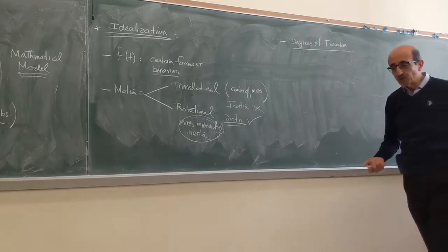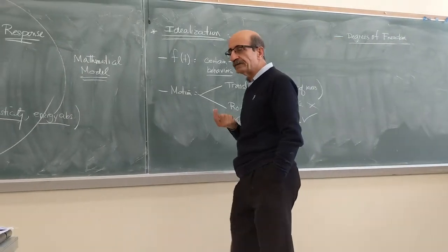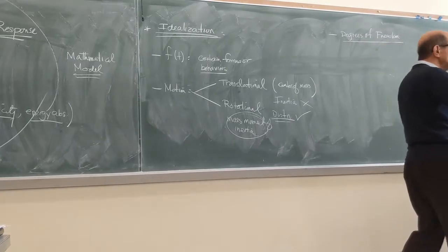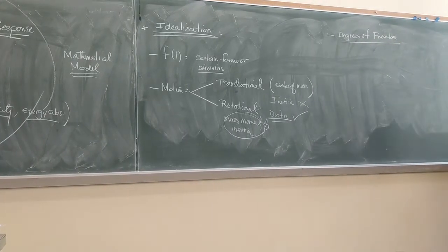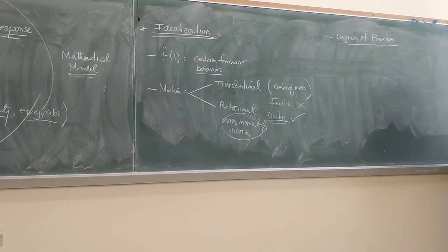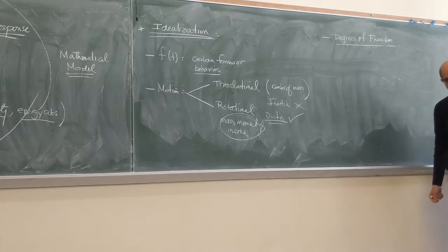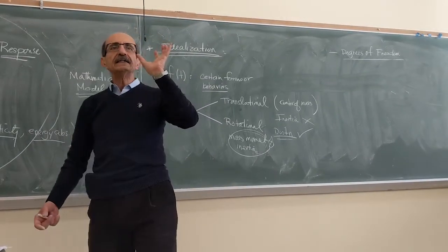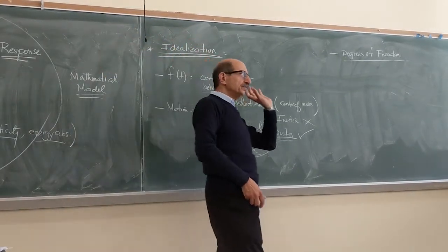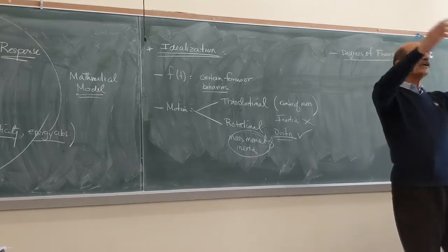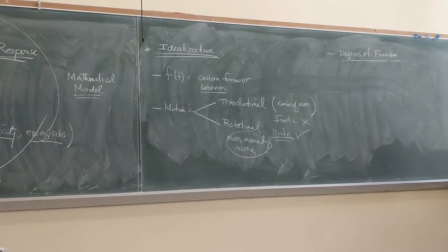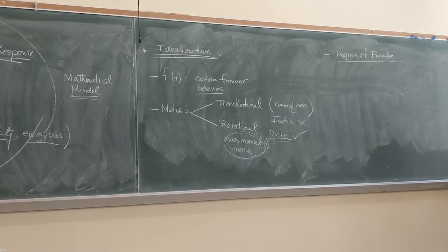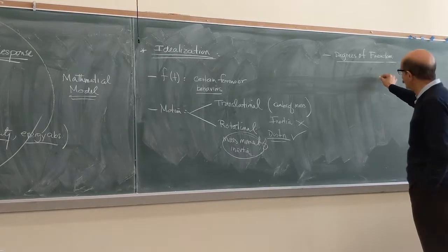It becomes much more simple when you think of it this way: if you know that there is a dominant shape that a structure has when it goes through deformation, in other words, there is one independent deformation according to which the rest of the structure can be defined, we call that a single degree of freedom. Let me make it more simple.